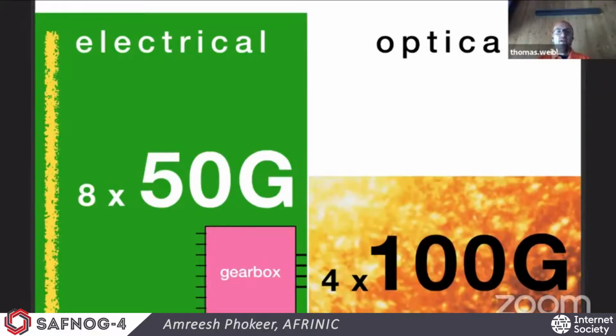There might be the question now, hey, why don't we just run 4 times 100 gigabit on the electrical side? In theory, this would be possible, but it's way cheaper to put an ASIC into that transceiver instead of having a high-speed enabled 100 gigabit electrical PCB, because for such a high-speed signal you have to increase the frequency, and basically you need really expensive PCB material, and it's cheaper to place an ASIC inside there. And that's the reason why the multi-source agreement who defined the transceivers stick to that solution, placing a gearbox on the electrical side.